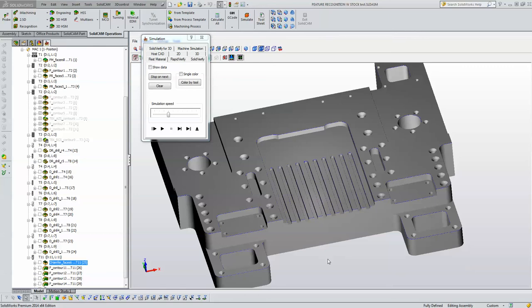This was done all in one operation and all at the proper depth as well. So, as we can see, using the feature recognitions instead of using all of the other operations, many times saves us a lot of programming time. I can do it the other way as well, as I've done it, but as far as the time spent doing it, this is a lot quicker.